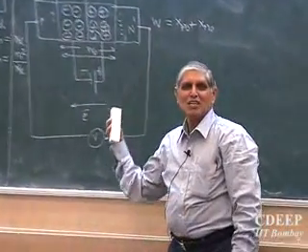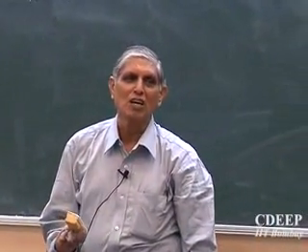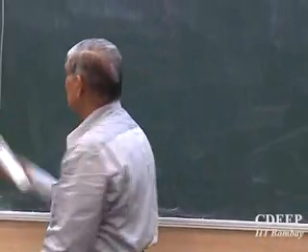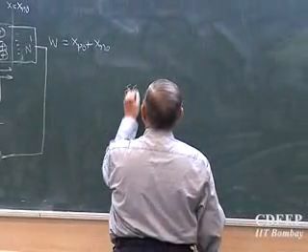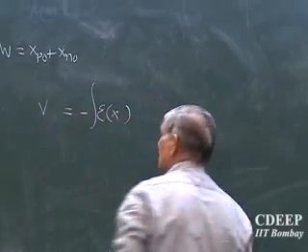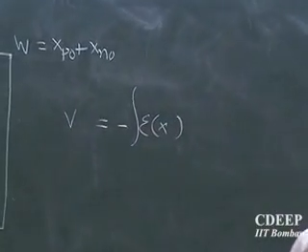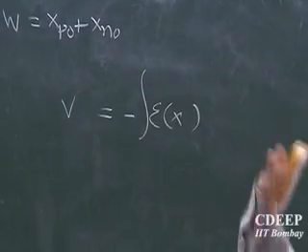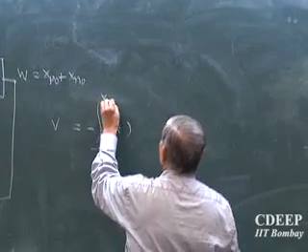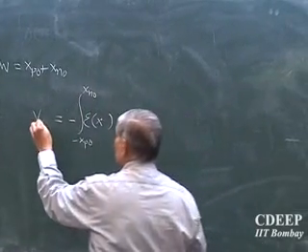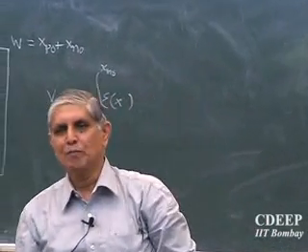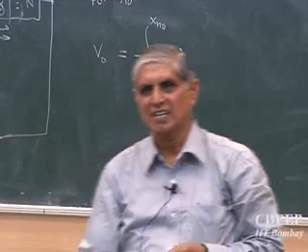Okay. So whenever diffusion occurs in a PN junction, a built-in field will immediately set in. If this is the electric field, then the voltage will be equal to the integral of E dx over the range you are talking about. What is the range in this case? This voltage is called the built-in voltage. Is that correct?